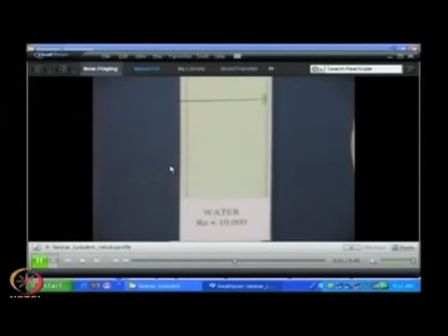Maybe let us just play it again to look into the experiments a bit more carefully. So the first experiment is with a very low Reynolds number, and if you see what is happening in these experiments, you have a regular, orderly motion. So layer by layer the motion is there, and because effects of the wall are propagating into the fluid towards the center line, you have that parabolic sort of distribution.